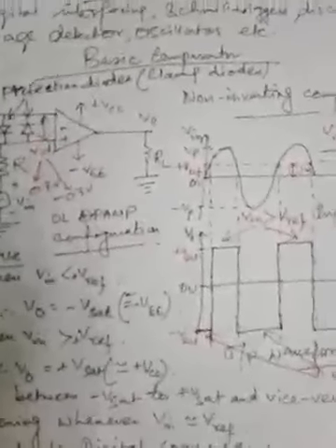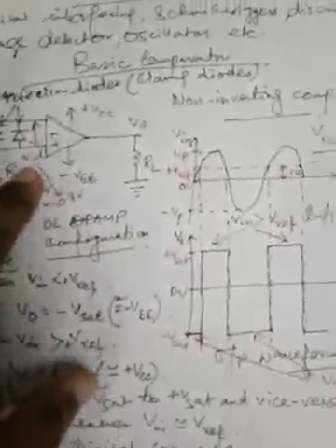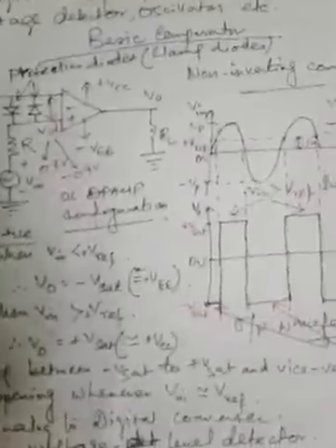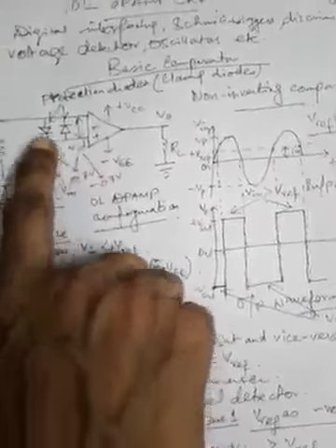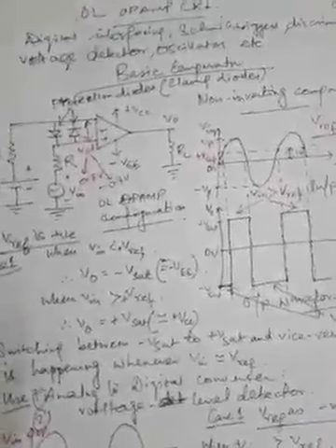Now there are some op-amps with built-in input protection also. In such op-amps, these two input diodes are not necessary, where the facility of input voltage protection is already built inside the op-amp. But if it is not there, then we should use this type of diode connection external to the op-amp, which will work as clamp diodes. Because if, due to variation of input voltage, VID is generated between the two input terminals of the op-amp, and that VID provides the minimum barrier potential of 0.7 volt or minus 0.7 volt to either of these two parallel diodes, then once getting this value across it, the diode will reach its cut-in voltage, and thereby it may conduct.